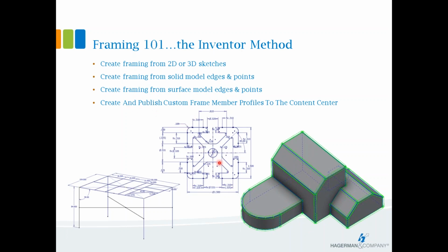And then also you can take your own custom shapes and publish them. Everybody's familiar with the almighty 80-20 shapes. So you can take those shapes, publish those into the frame generator engine as well. What you get out of the box are pretty much your standard shapes. You've got your I-beams, W's, L brackets, T brackets, round, square, and rectangular bar stock, and solid or tubing stock and solid bar stock as well. So if you need something custom, you can certainly plug that in and use that.